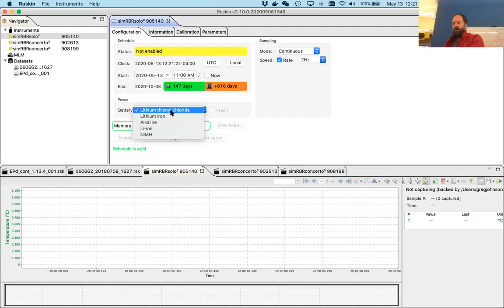And I want to hold up the battery which is the worst for this. It is another manufacturer of lithium thionyl chloride called Saft. And it's otherwise a very good battery. It's a Saft LS14500. It has all the same datasheet characteristics as the Tadiran, but if you put it upside down in cold water, you will actually find that it passivates, and those of you who have used this battery may have been bitten by that particular problem. So that's why we always ship with Tadirans.